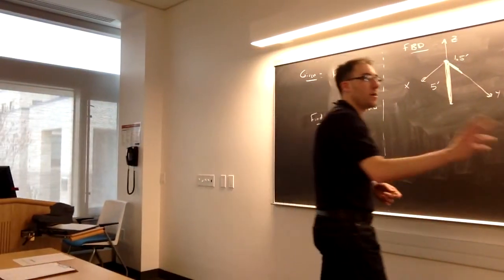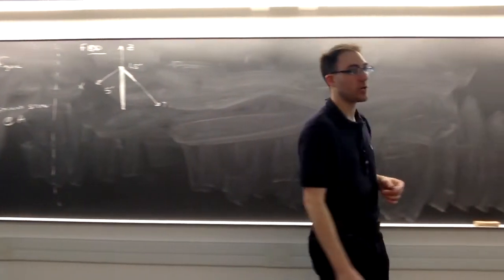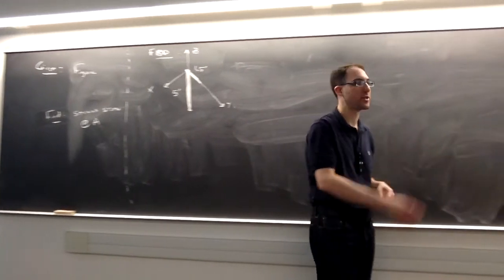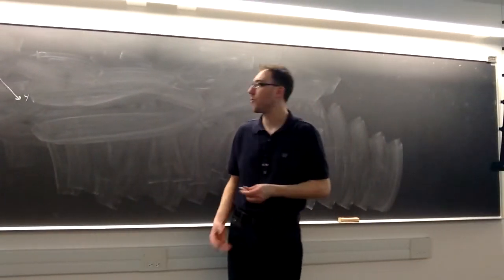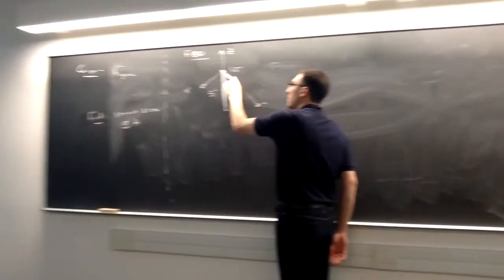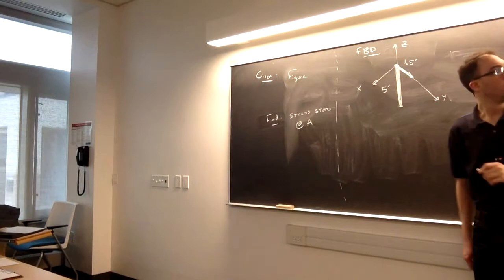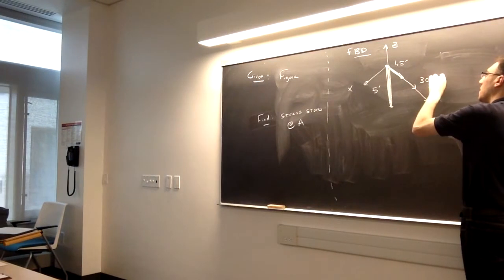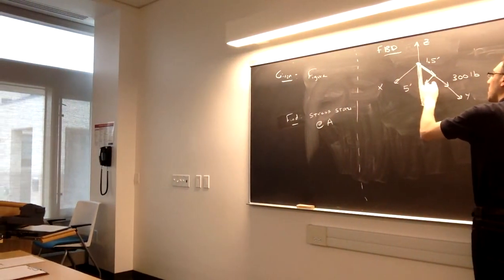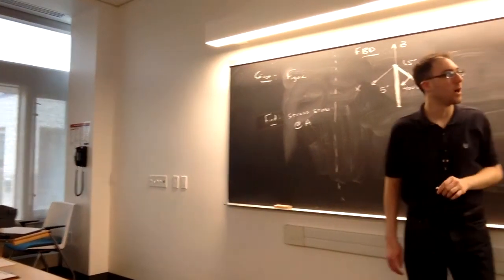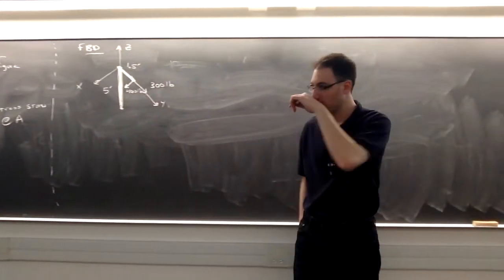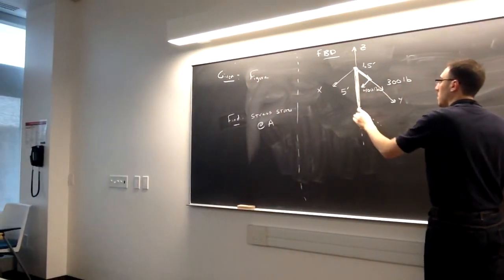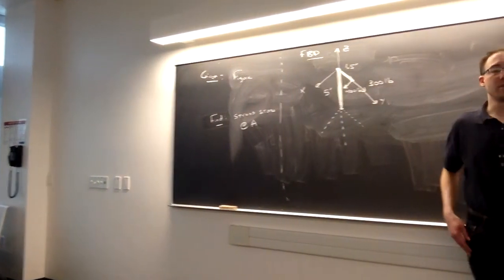So I don't need to solve for the reactions at the bottom where it's built into the ground, because in this picture I'm cutting it off before I have to see what those reactions are. So I'll start with what my applied forces are. Well, I have 2 of them applied at the end point here. I have that 300-pound load in what I just called the Y direction, and a 400-pound force along what I'm calling the X direction. Right, so those are my applied forces.